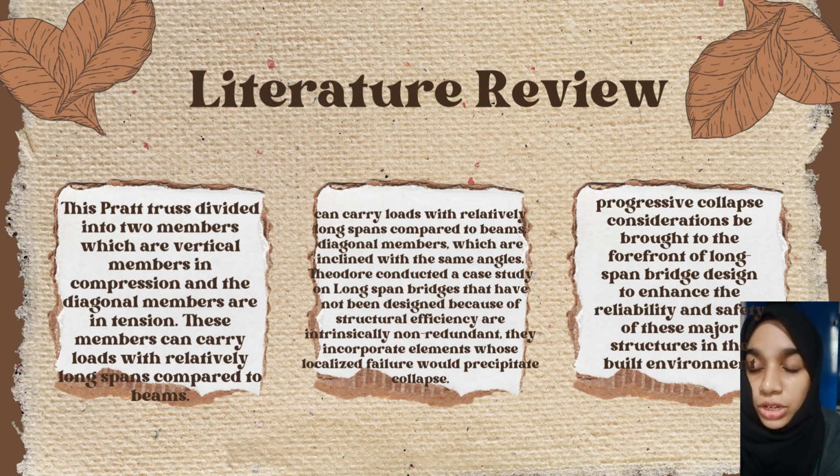There are also long span bridges that are susceptible to progressive collapse due to the loss of a series of adjacent members as a result of a single loading event. In either case, this class of structure may be termed to have single point vulnerability.